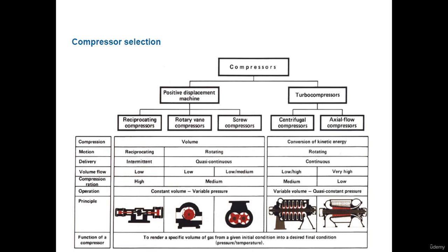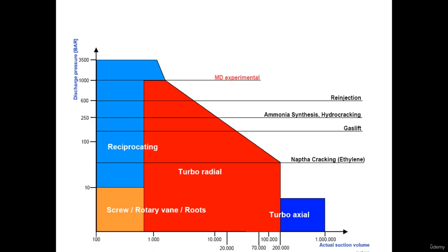So you have the gas analysis, the gas composition, and on the other side, the discharge side, you have to specify the requested discharge pressure. That's all. All other parameters, the discharge temperature and absorbed power, will be calculated by the supplier. If you don't want to calculate it, it's still better to know how many stages, for the desired final pressure and temperature.